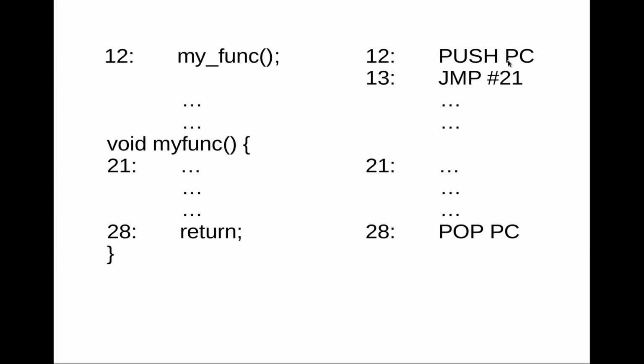And so it turns out we need to not only do arithmetic to deal with the stack pointer, because this in itself has some arithmetic dealing with the stack pointer, we would need additional arithmetic to deal with the program counter. And if you try and work out some instruction to do that all in one single set of microcycles, well, it turns out you need a hell of a lot more than 8. And in fact, we'd also need some temporary registers. So unfortunately, with my very simple CPU, this approach isn't going to work.